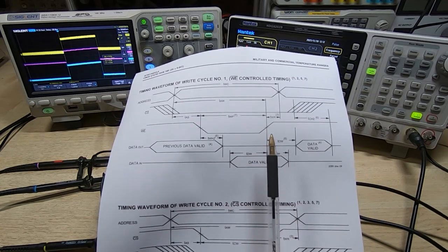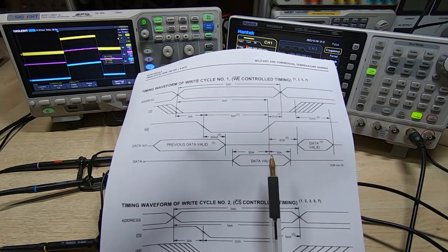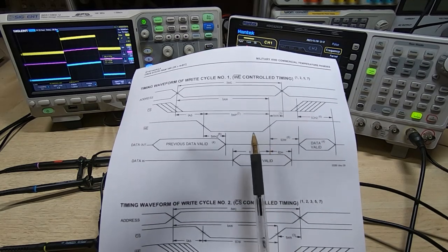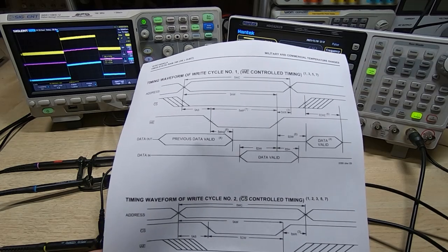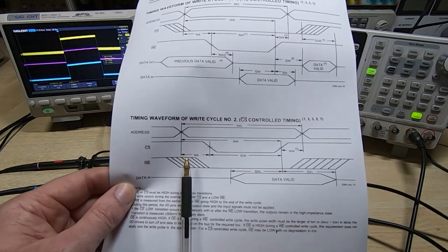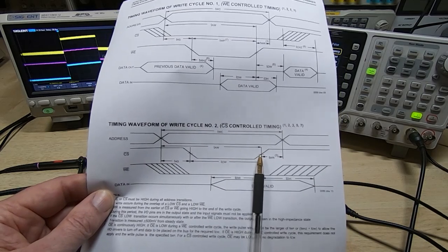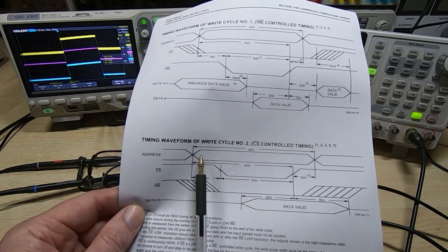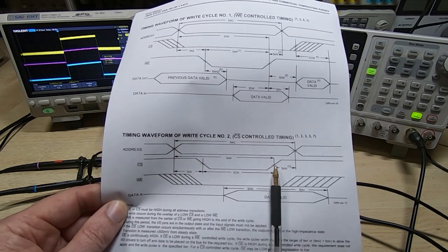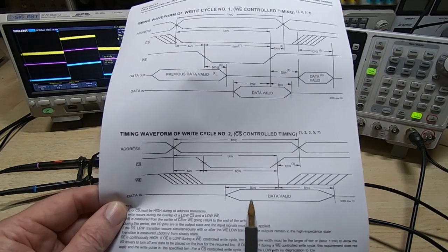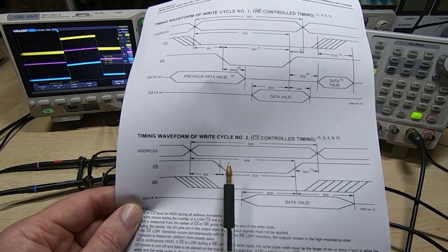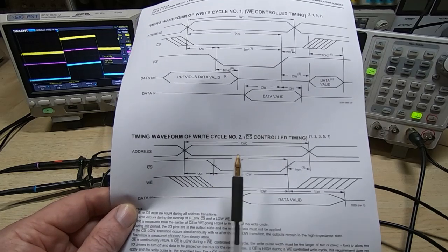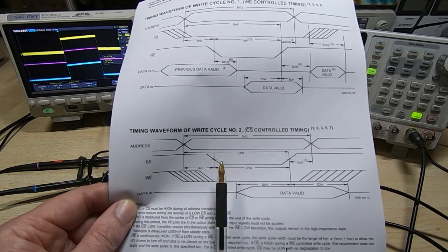Also, if you're introducing artificial delays using external circuits, those external circuits are also made from TTL devices that can start to introduce similar types of issues. So these timings are usually quite short, they're talking nanoseconds, and normally these individual steps within a cycle are controlled from the clock cycles of the clock going to the processor. It's all tied together to make sure everything's choreographed correctly.